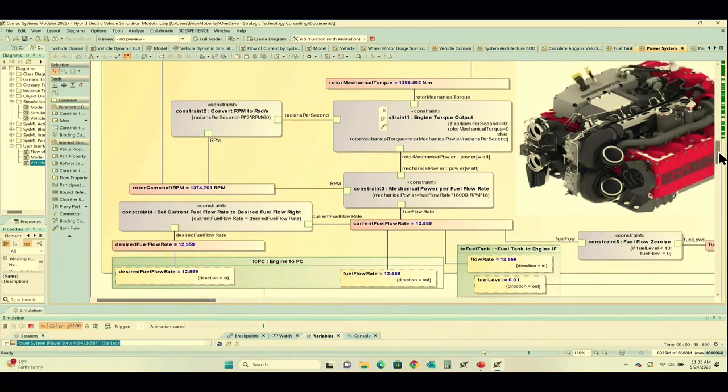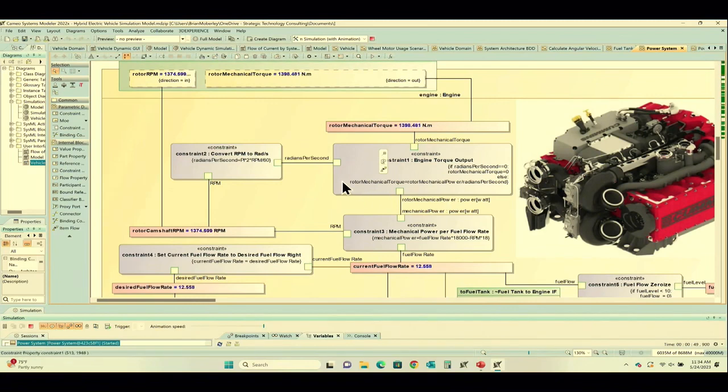But it does that knowing the RPMs as well. When you know the RPMs, you can convert that to radians per second using a simple equation: pi times 2 times RPMs divided by 60, right? That produces how fast the generator is turning in radians per second, which you can then take into this equation as well. We threw in an if-then-else statement. I think that was for purposes of getting close to 0, so we didn't have some weird things happening with 0 values. That's why we have an if-then-else statement.